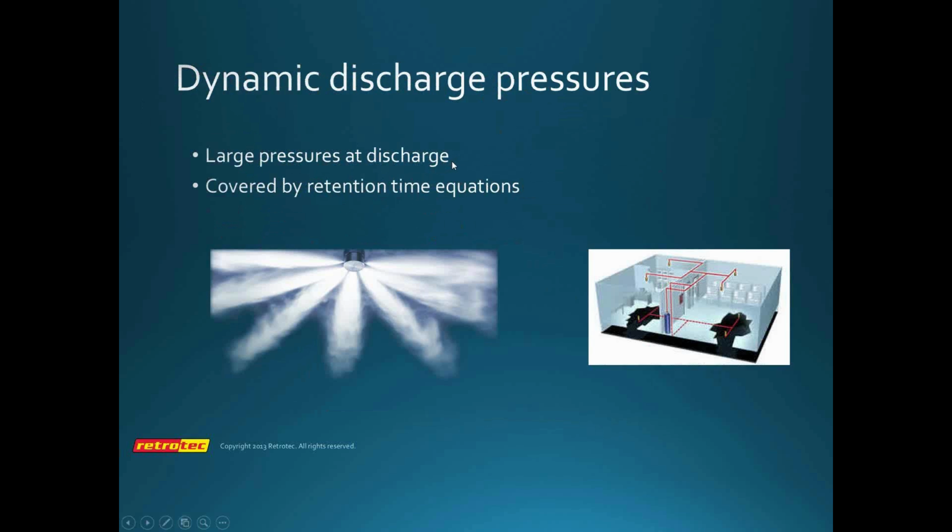The other point here was that there is some agent that's lost during the discharge, but because we have cooling both with halocarbons and to a lesser degree with inerts, we don't have quite as much agent loss as we thought initially, because the decreased volume of the agent being put into the room actually accommodates more agent.